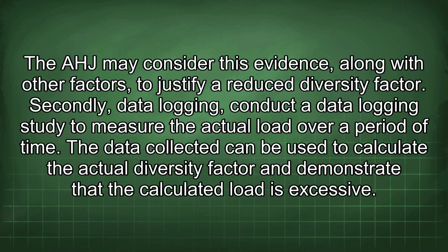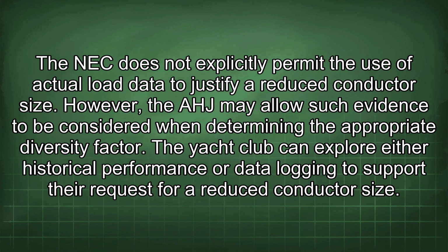Secondly, data logging. Conduct a data logging study to measure the actual load over a period of time. The data collected can be used to calculate the actual diversity factor and demonstrate that the calculated load is excessive. The NEC does not explicitly permit the use of actual load data to justify a reduced conductor size. However, the AHJ may allow such evidence to be considered when determining the appropriate diversity factor. The yacht club can explore either historical performance or data logging to support their request for a reduced conductor size.